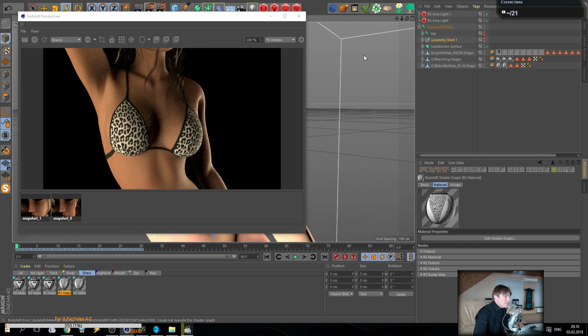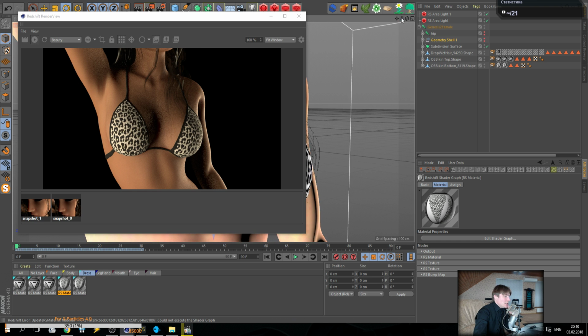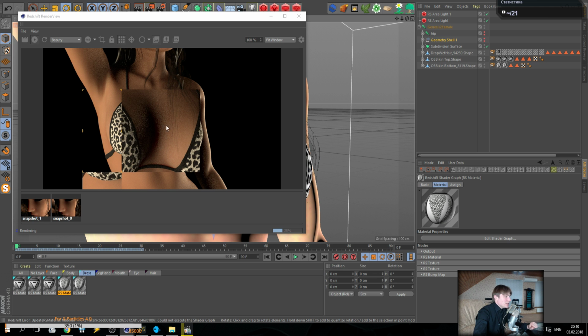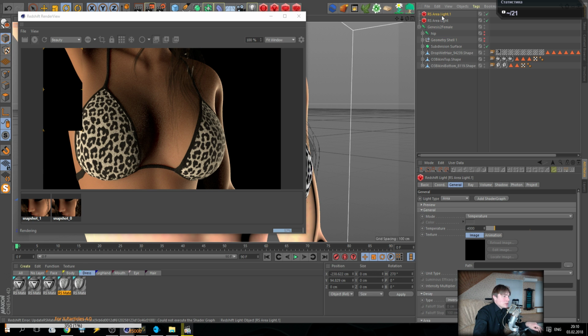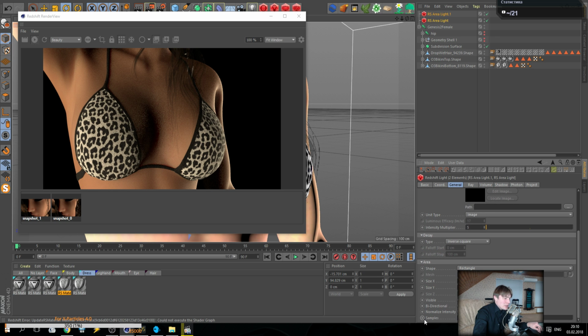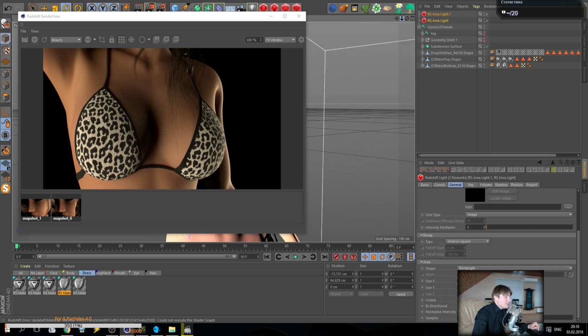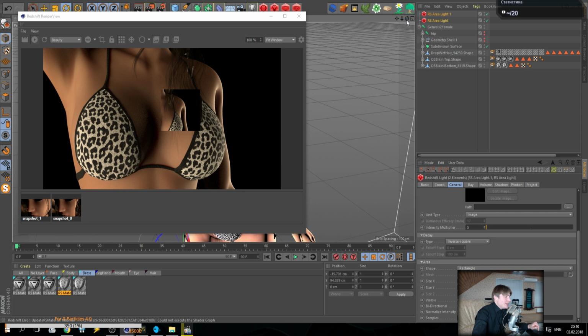Okay, look at this. Look at this, it's very nice. And how to reduce the noise? You can see a noise, it's very simple. We are going to the area light, select both of them, going downstairs, and here you have samples, area samples, just increase, I don't know, maybe 64. And okay, you see, now no noise and still very fast rendering. Just small tricks. Very nice.